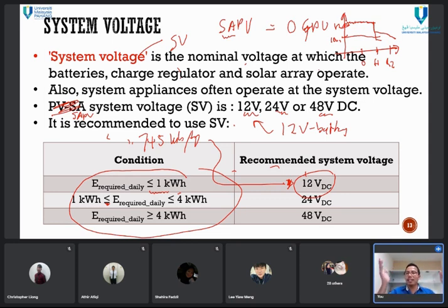Then your device stops and you say, not enough battery. It's actually not that the battery is not enough. It's you who chose the wrong size of battery system voltage. That's the reason. One is the load; we don't calculate the load. We buy modules, buy batteries, use everything you want to use. Oh, not enough batteries. Actually not. We are not planning it properly, before we do the buying, before we purchase the things, before we do the installation.